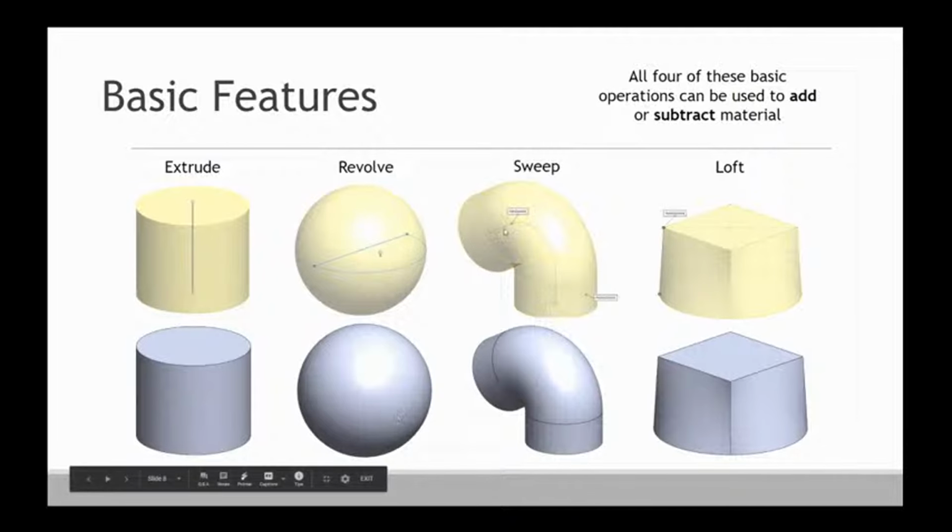Then we also have swept extrusions, which you can use to make more funky shapes. And then, of course, the funkiest so far is the loft, which is how we make complex geometry between two different shapes of faces. With a loft, you can go from a circle up to a square, and it slowly morphs this circle into this square shape, basically like an integral of the difference between them. That's pretty neat. These are just some examples of the kind of stuff you can do.